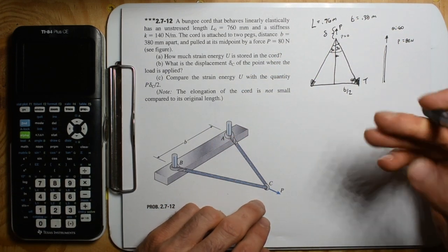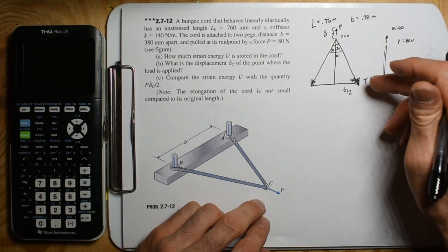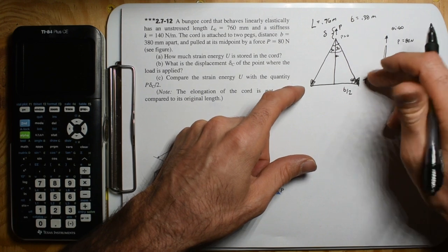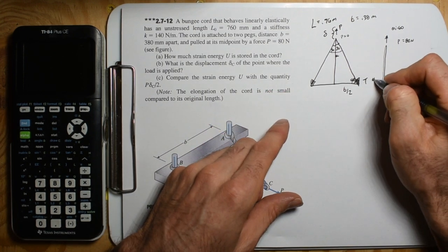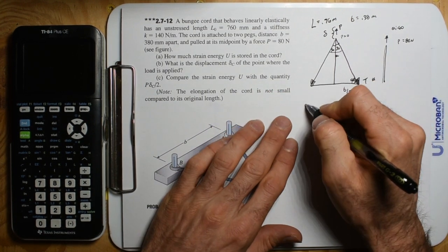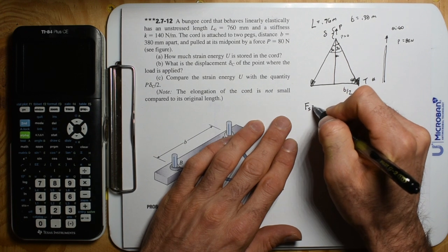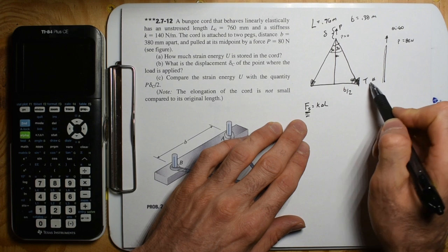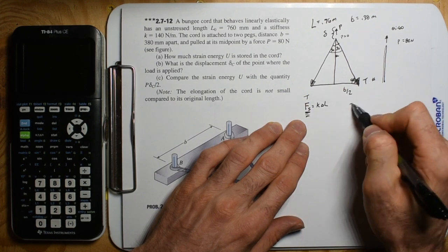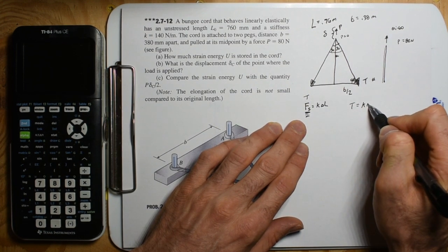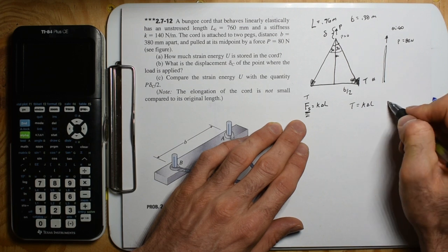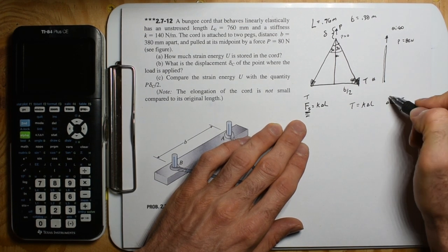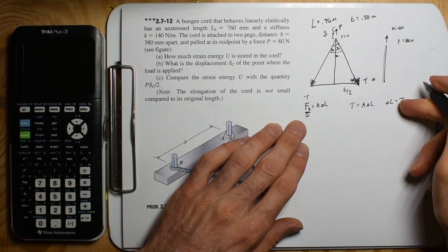So why the iterative process worked is that when you calculate the tension initially, you're going to get a huge tension. Now we go to the spring equation that says the force of a spring is K times the change in length. This is the tension side, so tension is equal to K times change in length. But we want the change in length, so change in length is equal to the huge tension divided by K. So we're going to get a huge change in length, which is wrong.